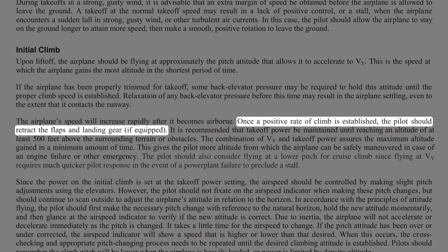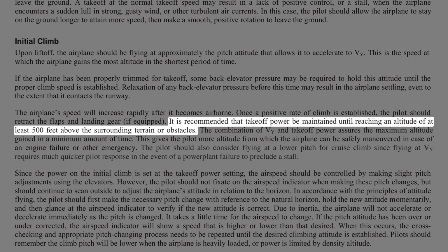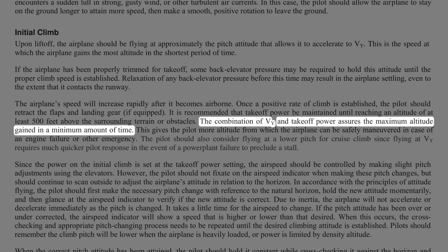Once a positive rate of climb is established, the pilot should retract the flaps and landing gear, if equipped. It is recommended that takeoff power be maintained until reaching an altitude of at least 500 feet above the surrounding terrain or obstacles. The combination of VY and takeoff power assures the maximum altitude gained in a minimum amount of time.